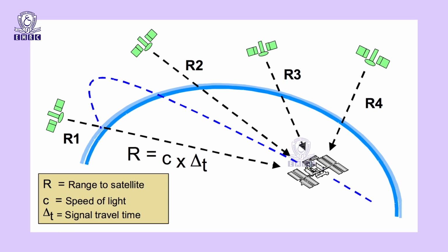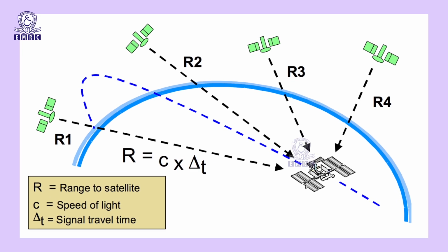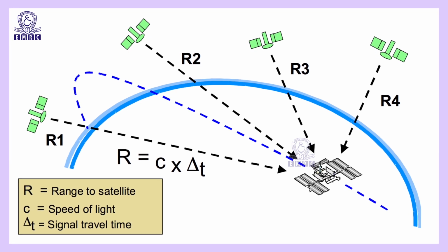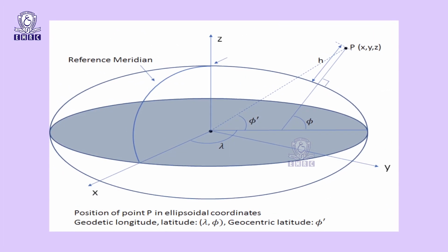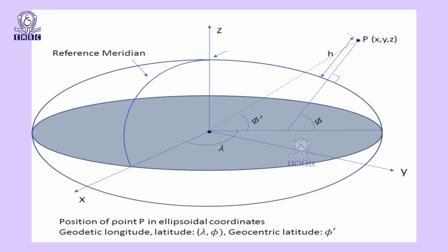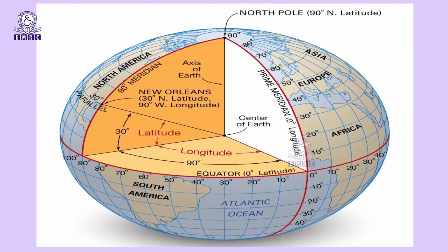So, whilst position fixing is possible, it is unreliable unless it is assumed that the receiver is at sea level on the surface of the earth, because it is almost certain that only one of the two derived points would be near to the surface of the earth. So, fixing is possible, but only in 2 dimensions, 2D fixing in latitude and longitude. With at least 4 satellites visible and their alignment good, the 4 spheres will intersect at only one point in space. So, the receiver position can be accurately fixed in 3 dimensions, 3D fixing, that is in latitude, longitude and altitude.